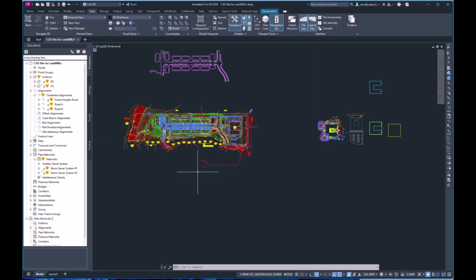So what we're going to do now, we're not going to explode. We're going to use a command called burst. And if I hit that, it cycles through bursting the blocks. Now I have run into where I get 2,000 or 3,000 or 4,000 blocks, and it takes a while for them to all get exploded.